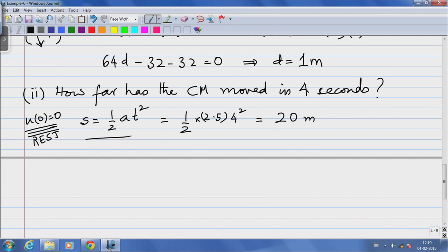Notice how this equation is what you would usually use for point particle kinematics, and we are dealing with rigid bodies, but an equation that was originally intended for point particle kinematics, distance travelled as a function of time, would perfectly apply here, because the body has only two translational degrees of freedom, and the rotational degree of freedom is completely shut out. The angular acceleration in that direction is 0. Not just that, the body is actually exhibiting only one dimensional motion. So, the acceleration in the y direction is also 0.